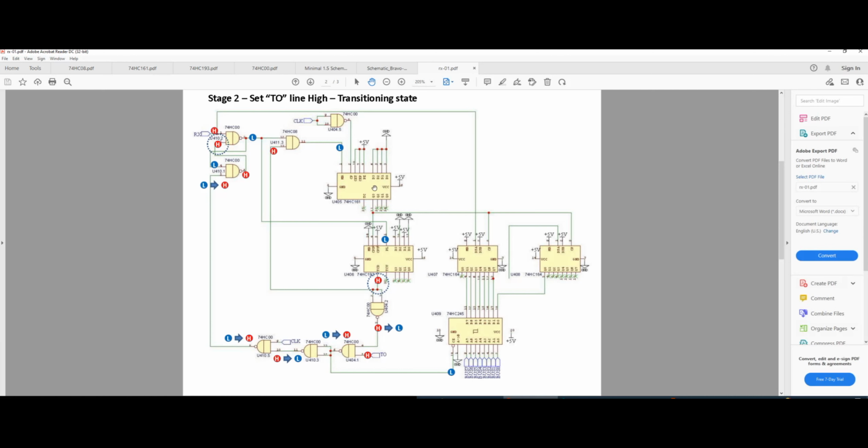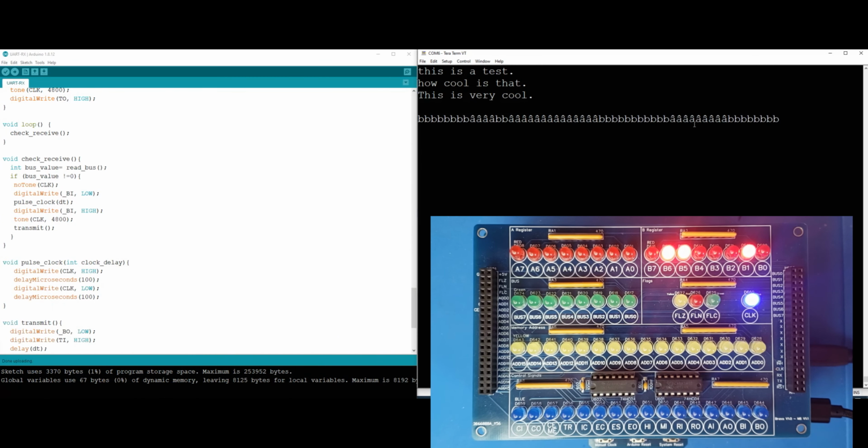So essentially, if the timing between the characters you're sending to Bravo is faster than 160 clock pulses between them, then obviously those characters are not going to be fully received, and we're not going to see the correct character on the bus. What you see here is just the result of the lower clock speed. This is not going to be an issue, because in the final version we're going to run the whole computer at a much higher speed, so you're probably never going to see that.